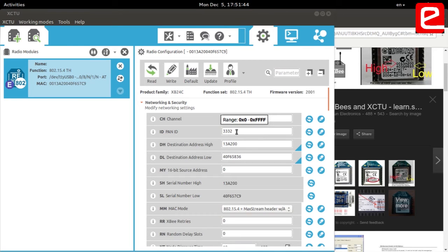At one time, if you have multiple adapters, you can connect the multiple adapters. Both the zigbees can be connected to different USB ports, and then you can add both the zigbee modules. If I have one more USB adapter, this same block will come, and you will see one more zigbee device can be added here.